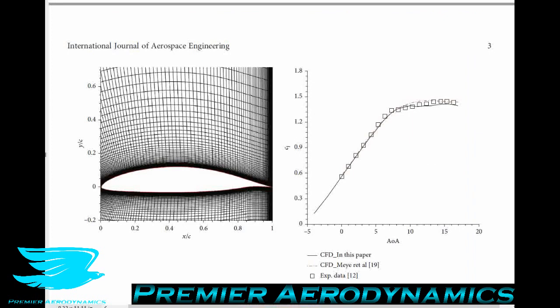The reason why the Mach number is quite important is because if you have a Mach number of 0.3 or more, as a rule of thumb, we say that the flow is now compressible. The reason why we say that is because at a Mach number of 0.3 or above, the density of air will change by about 2% or more, because the flow in front of the airfoil, or whatever object we have, is now being squished. The reason why is because air can only really move so fast.